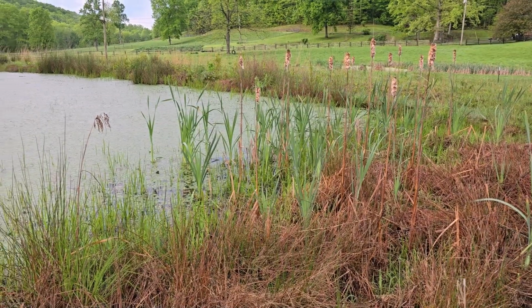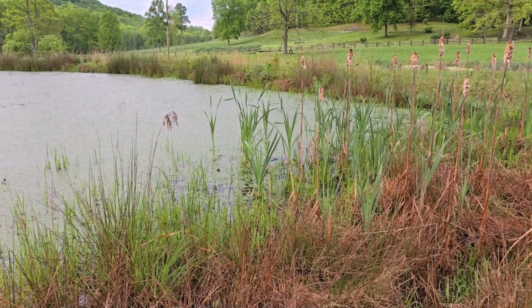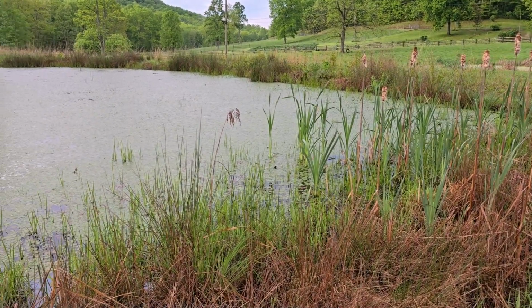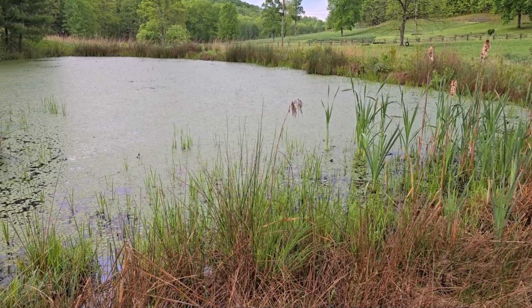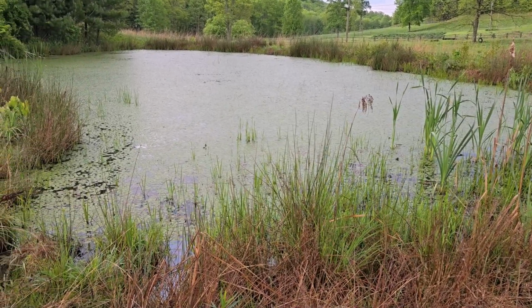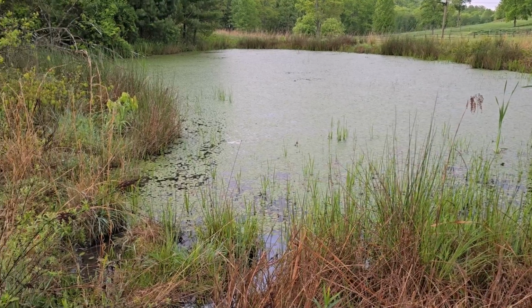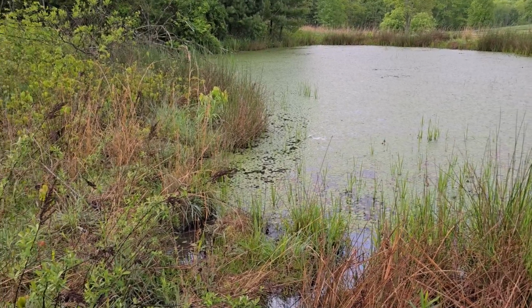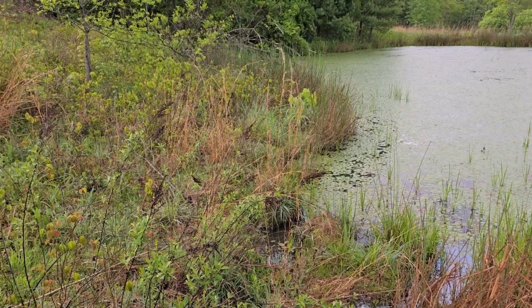My wife and I built this emergent wetland on our farm 28 years ago. The dozer operator shaped a 2-foot-high dam that has a 12-foot wide top with gradual slopes and a drop pipe water control structure along with a wide spillway. For maintenance, I've mowed the dam twice a year since it was built. There have been hundreds of thousands of ponds and wetlands that have been built across North America, and most every one of these has been built using a dam. Now, these dams should be inspected regularly, and the maintenance should be completed as needed so that these ponds and wetlands can last forever.